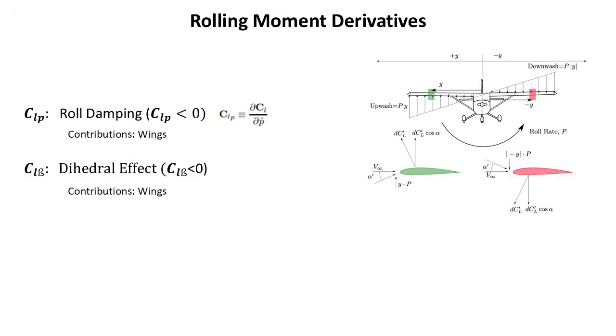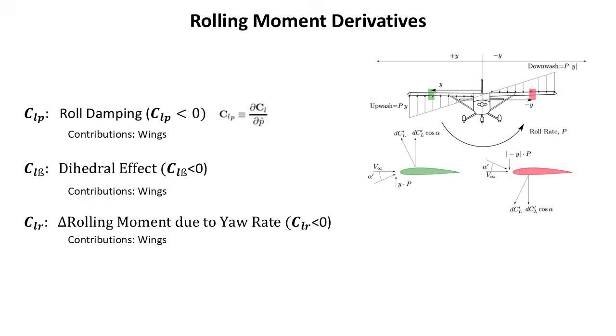This is a common aerodynamic response called adverse roll and can occur in an aircraft without specific design elements like dihedral wings to counter this effect. CLR describes the rolling moment generated due to a yawing motion or rate and is usually negative in aircraft that have minimal dihedral in the wings. In adverse yaw, when the aircraft yaws, a rolling moment in the opposite direction occurs because of asymmetric drag between the wings. CLR is where, for aircraft with swept or dihedral wings, yaw-roll coupling can become problematic.